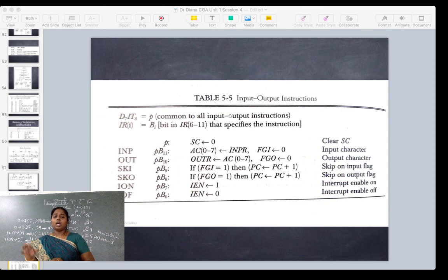Clear? So, the interrupt enable flag is used by the other devices to communicate with the CPU, and the CPU waits until the interrupt is raised. When an interrupt is there, it services that interrupt. It does whatever the interrupting device asks for, and then it continues with its normal program execution.